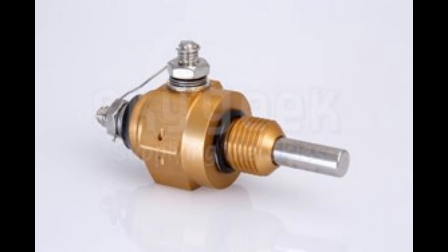Typically, the easiest way to do this is we're going to wrap a piece of safety wire between the two electrical terminals. That way we know those terminals are at the same potential. In other words, there is no voltage differential between them, which would cause that squib to discharge.